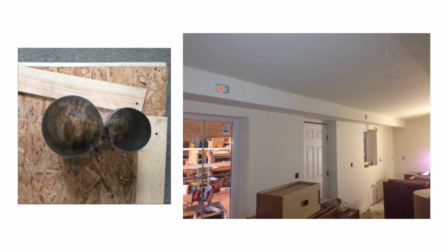The registers here are going on, and they're designed to move air across using the surface effect across the ceiling. So they blow out this way up against the ceiling. And by the time the air drops, it's moving slower than terminal velocity. So it's not blowing cold air on people.